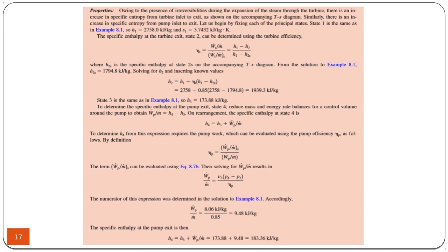So we can calculate the actual turbine exit enthalpy, as opposed to the isentropic exit, from this equation. The actual turbine exit enthalpy is greater than the isentropic turbine exit, because of the irreversibilities such as friction, the steam leaves the turbine at a higher energy. So instead of converting a lot of the energy to work, some of the energy has been converted to an enthalpy increase because of the friction.